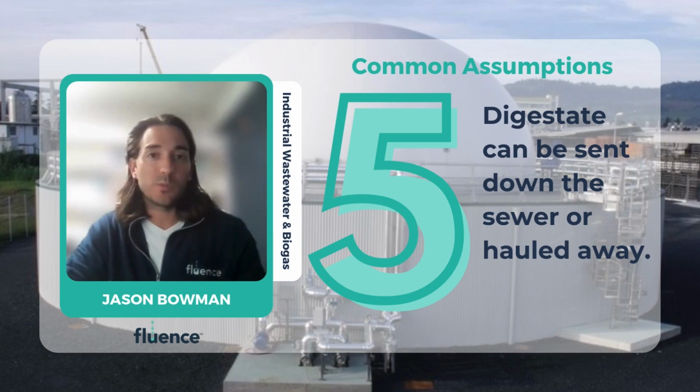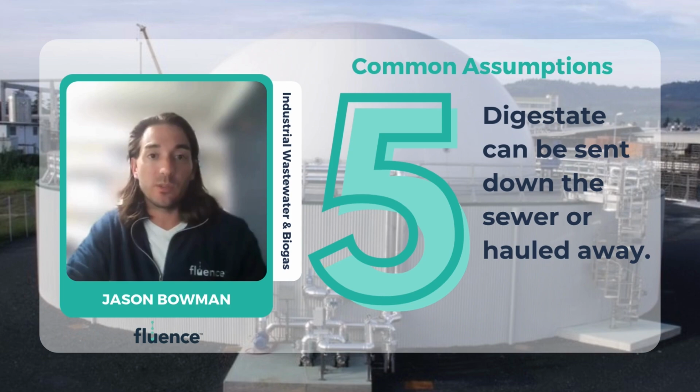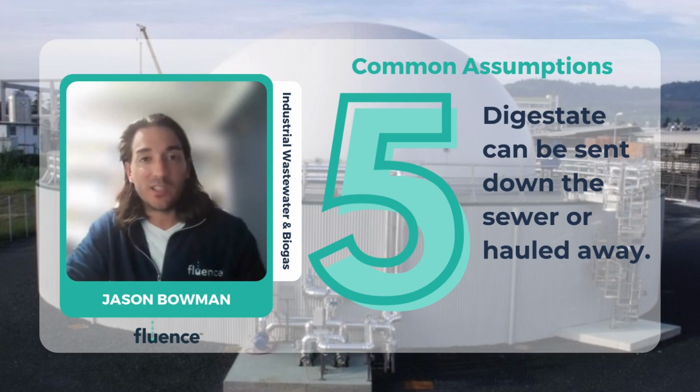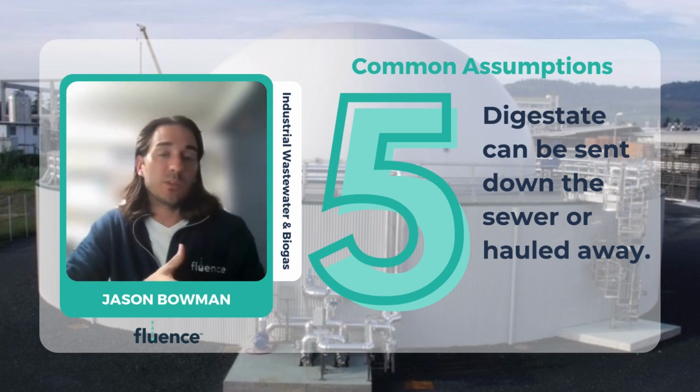Let's say this facility is producing 60,000 gallons a day of digestate. The equivalent COD load to that municipality is almost like having an additional 1 million gallons a day of flow. The equivalent ammonia load to that municipal facility is almost like having 3 million gallons a day of additional load. So in other words, that 60,000 gallons a day is more like having a 1 to 3 million gallon facility in terms of the total pollutant load. So this is why digestate can seem very costly to treat, because you're basically having the same pollutant load as